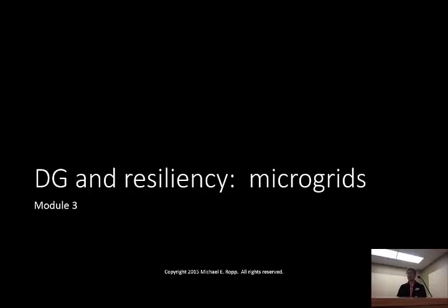So if I've got, let's say, an overhead feeder, and I have no caps on that feeder, I wouldn't have to worry about islanding. I would say you're free and clear. You can't get a VAR balance if there's no VAR source. And if your load is strictly inductive, once the island is formed, the frequency is going to take off. It's going to go up even without active anti-islanding, but add the active anti-islanding in there, and it's going to go up that much faster. So if there's no VAR source, no caps, you're probably home free. Does that answer both of those questions? That's for inverters. Yes, that is for inverters.